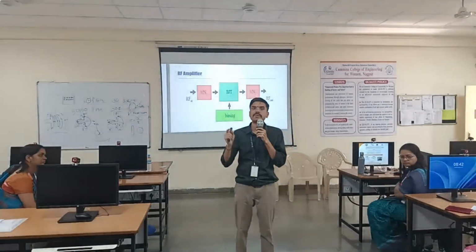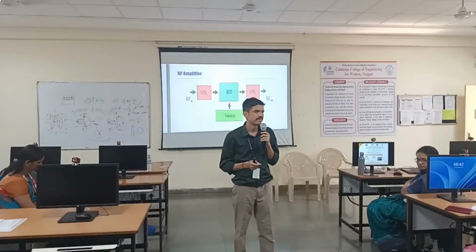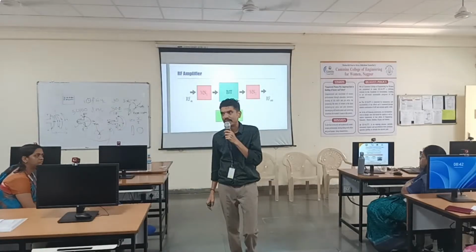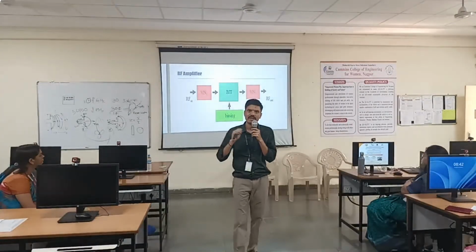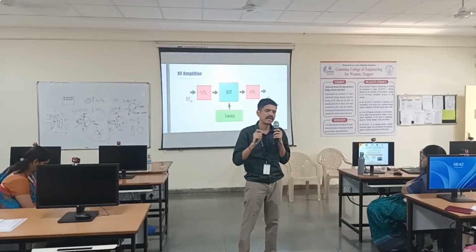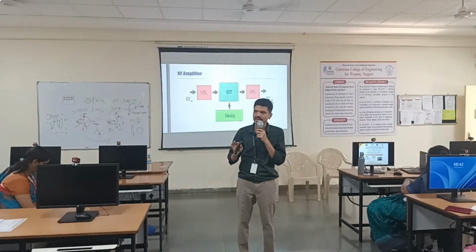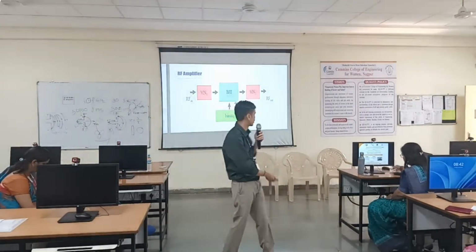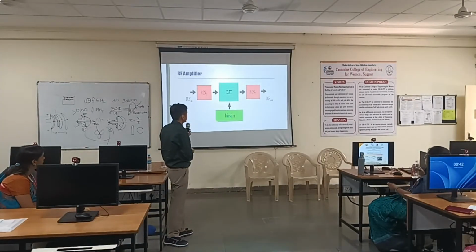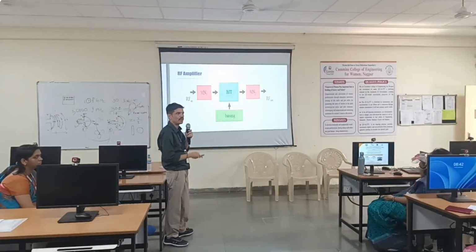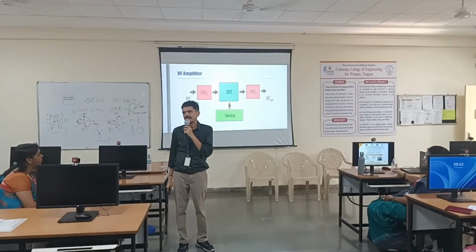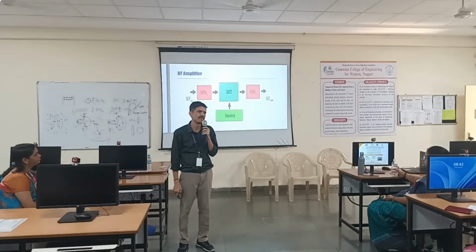whatever amplifier you are going to design at RF, what are you actually doing? If somebody asks you to design, let us say, a microwave amplifier, I'm not saying low noise or high power, class A, B, class E, F, whatever it is. If you are a microwave or RF amplifier designer, your life will move around this picture. This one, this one. So you have to design a broadband, low loss, matching network. So what is the job of the matching network? Why do we need it?